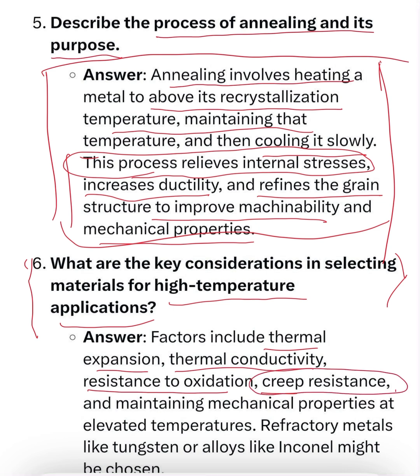For example, turbine blades are usually made of a single crystal nickel base alloy, so they have high creep resistance and maintain mechanical properties at elevated temperature.